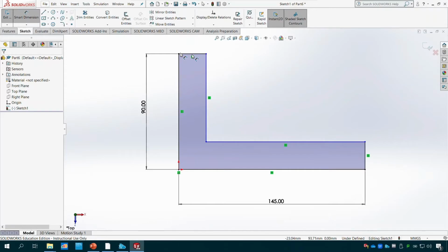So let me see how much it needs to be extruded. The amount of extrude is gonna be 72. And it depends on what method. In case you want to make it fully symmetrical, you can put it as a 36. In case you want to put it on one side, you can go with a 72. Let me go with a symmetrical with a 36.